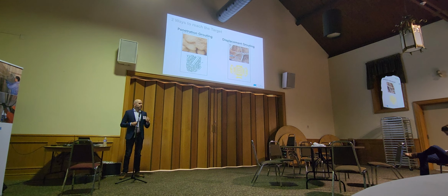And then you have another interesting idea, which I will show you later on in our reference project. After compacting, after you widen your arms, the soil is compacted around, and then there is only one way, and this is up. So you will also be able, with this type of grouting, this displacement grouting with resins, to lift up structures, but not by pump pressure, just by expansion pressure of the resin.